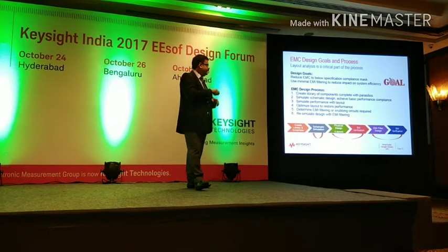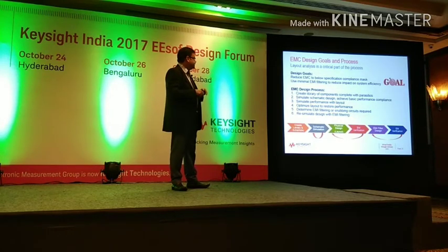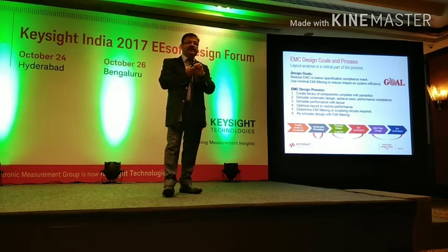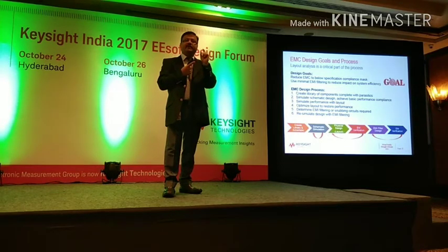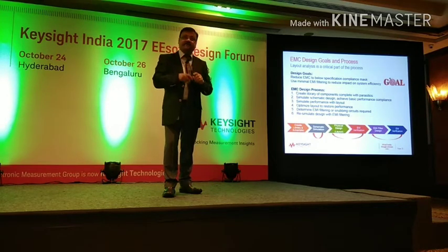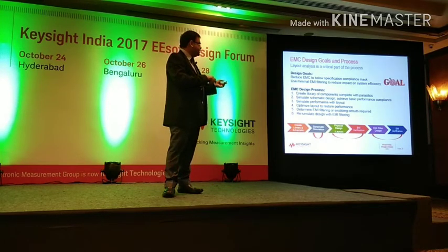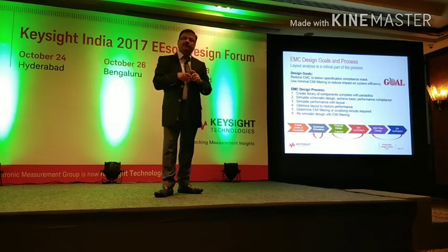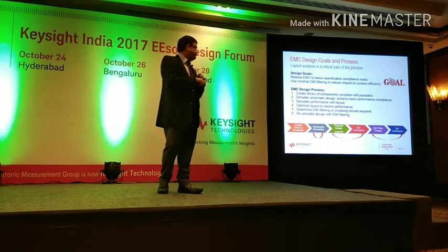So here's a typical process. Simple 6-step process. Create a library of components with complete parasitics, so that no component is treated as an ideal component. Yeah? All the components should be there with parasitics. Simulate schematic design, achieve the basic performance compliance. Whatever efficiency criteria, voltage criteria, current criteria you may have, go ahead and design that first.